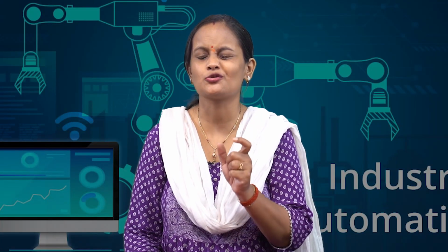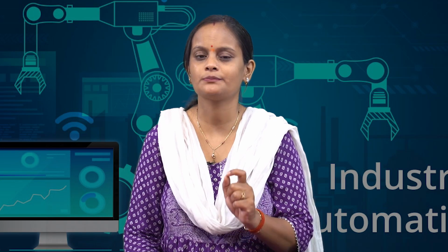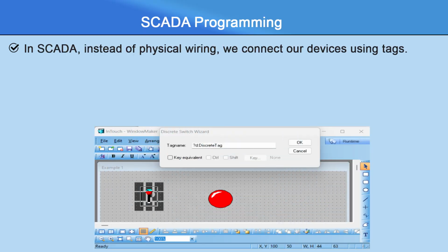Now the next step is to interface or connect this input switch to our output indicator, the output light. You have to keep this in mind that in SCADA, instead of physical wiring, we have to connect or interface our devices using the tags.